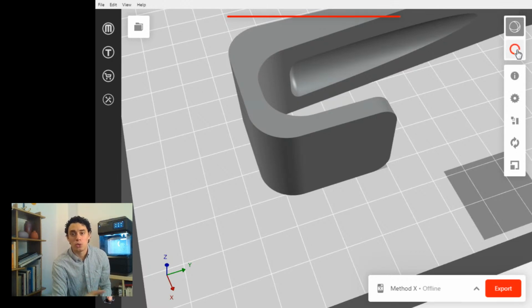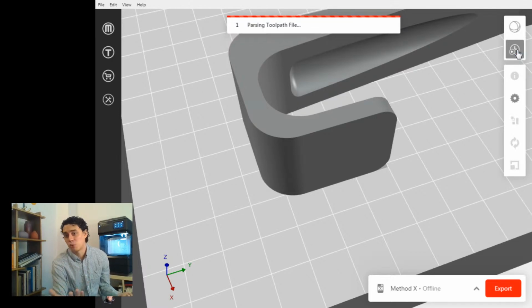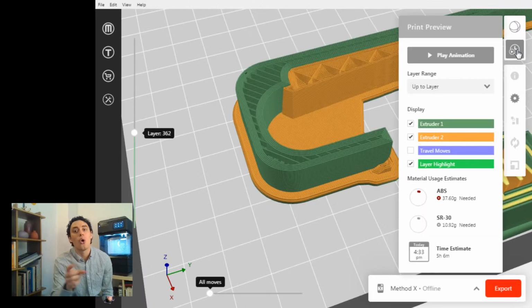Depending on what you're trying to do, depending on the development phase you might be at, there are times where you cannot get rid of the supports. And you can also use breakaway supports, which is something that we can touch on. I think there are whole MakerBot chats on just the types of supports that you could use. But yeah, it goes to 5 hours, right? So 2 more hours because it needs to create supports.